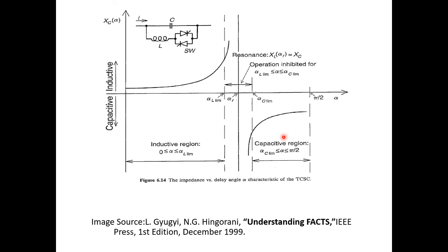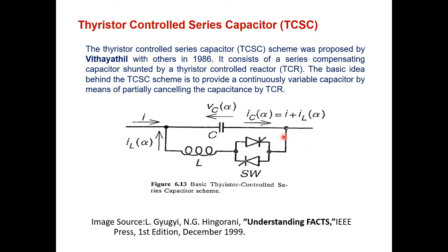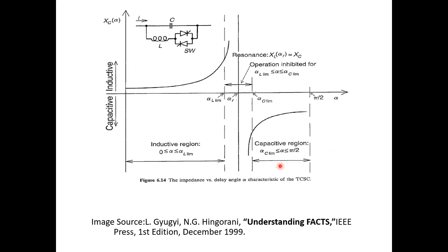Try to remember this graph. This one is for the part of which thing? TCSC. Controlling can occur with the help of this inductance that carries some current IL at an angle of alpha. Alpha is the firing angle in thyristors. Gamma is the turn-off delay angle in GTOs. Negative voltage will be there in this particular one.